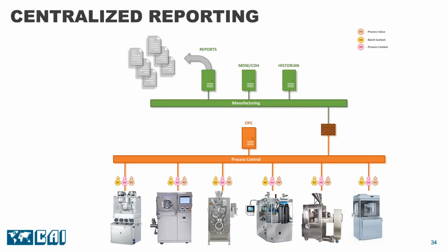With a little bit of work, we can contextualize and aggregate it, and store the max force, min force, average force, etc., and report on it. In the process, we have stored all the raw process data, and we have stored aggregates in the contextualized data historian, which can be used by other tools for analyses and support process optimization.